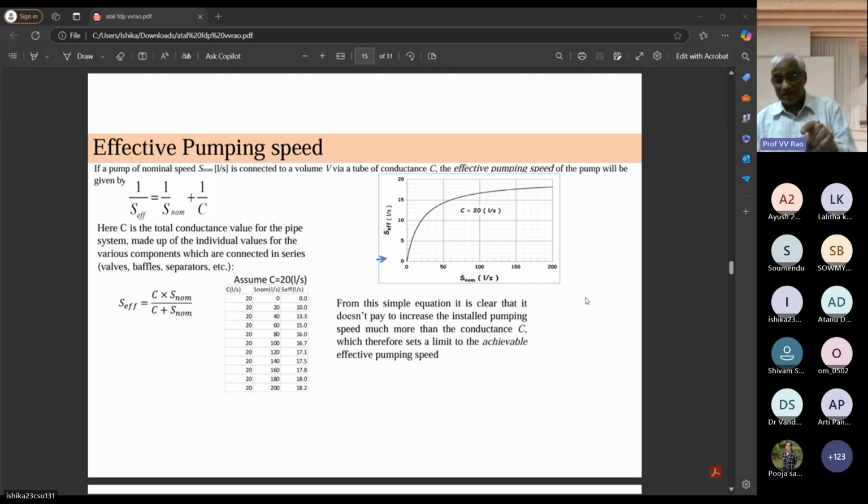But wanted contamination is always required. That is called doping. Doping is nothing but wanted contamination. You are actually contaminating pure silicon with p-type impurity. They are called impurities. That is also contamination, but it is required to make p-type or n-type and make the junctions. Then only you will have a non-linear IV characteristic. You will get diodes, transistors, etc. So that is the funda.